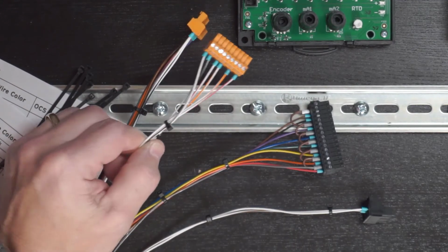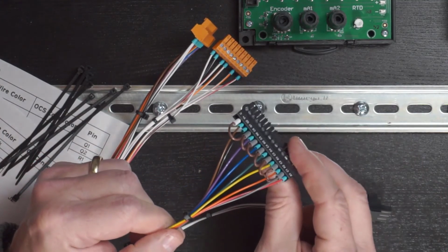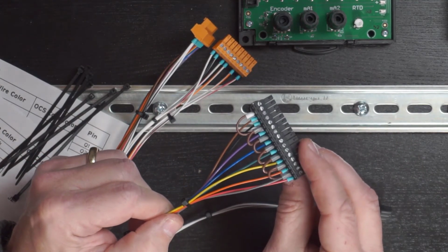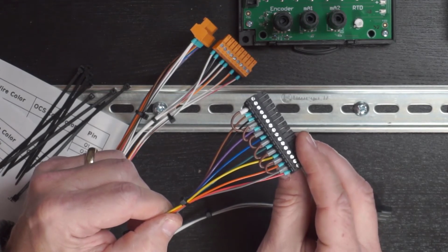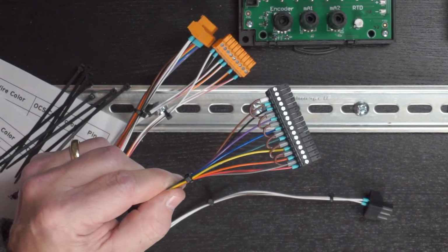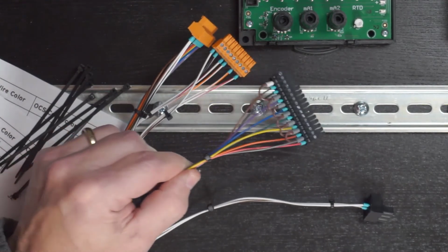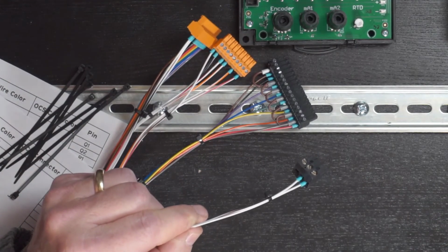Here's our output connector, as you can see, with the jumper assembly already installed there, connecting the V plus 24 volt signal everywhere it needs to go. And then in addition to a few pins on the output connector going to the analog side of things, two conductors exactly are going to your power cable to power your OCS.